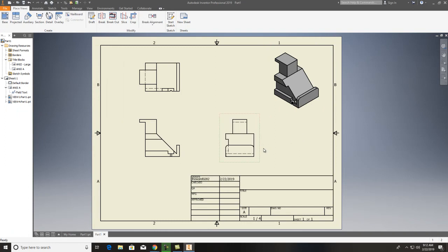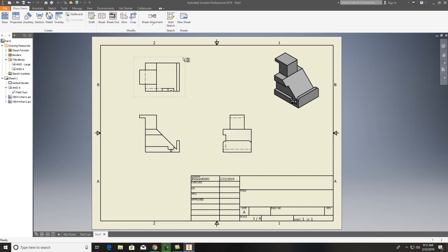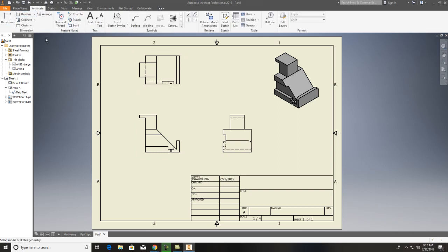So there's everything set up on this one, and now what I want to do is you go through and just put your basic dimensions in on this, and whenever you're doing dimensions, make sure that you think about this thing. You know, the front view shows your width and height, so you can go ahead and get your height in. You know what I'm saying? Go ahead and get your heights in on one of them. Over here shows your height and your width, so you can go ahead and get some width dimensions in. And this one here is going to show your width and your depth.